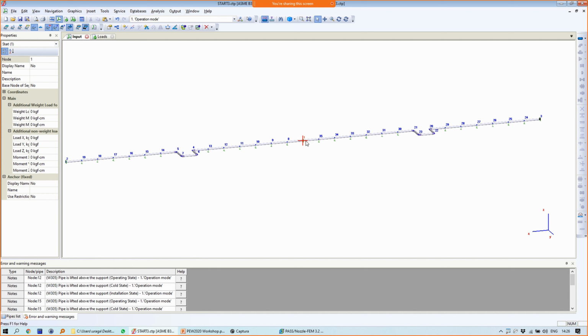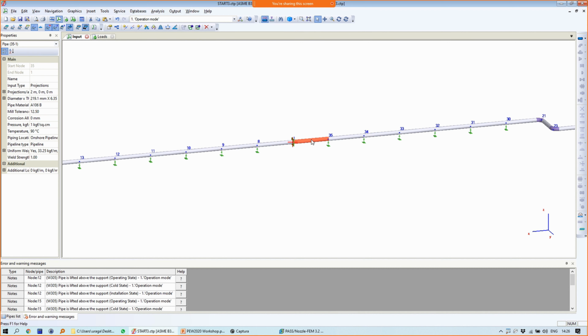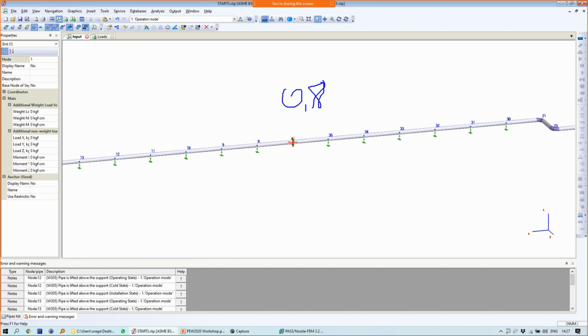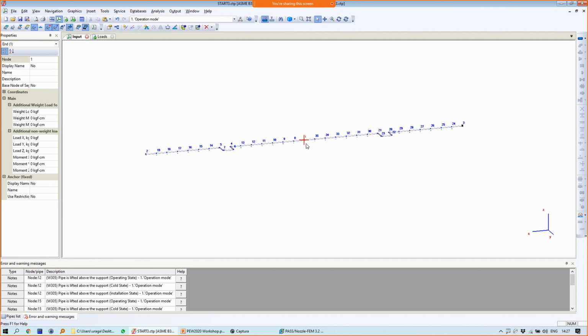Of course you can check all the situations, change the temperatures, change the friction factors, and change everything in this model, but it will take a lot of your time. So this trick with the factor 0.8 is much easier to use for approximate solution during the piping design. So as I said, it's widely used by Russian companies.